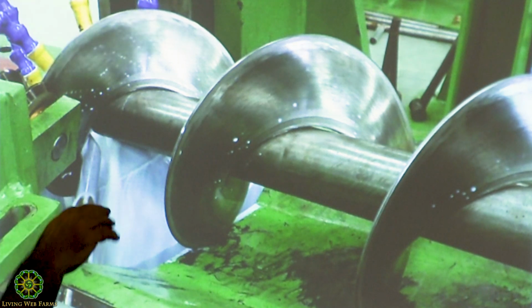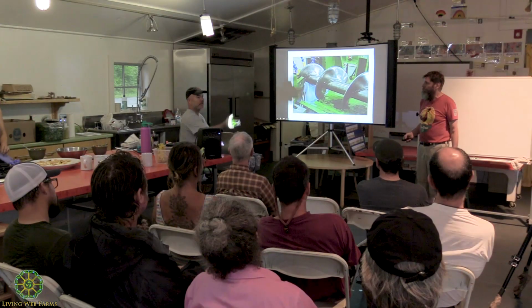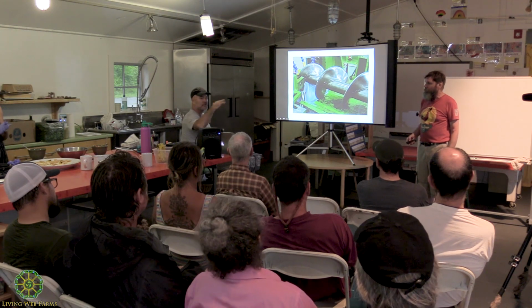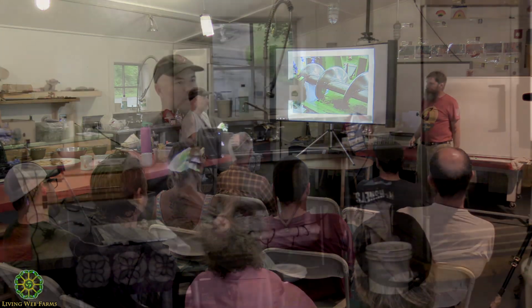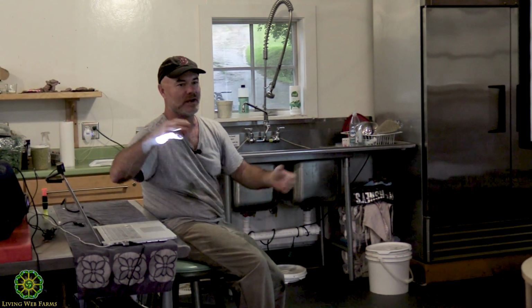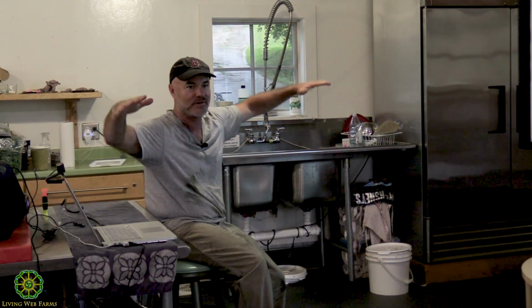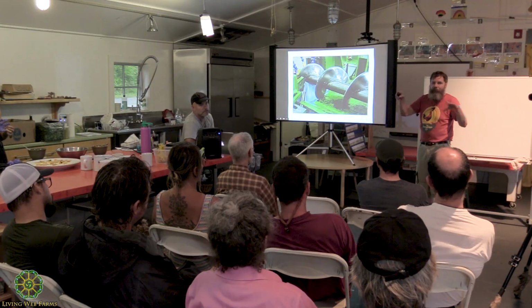If you lifted water over the draft tube, you've created a vacuum. Yeah. So you started that motion already, so you just need to move a very small section. Right. And that perpetuates it just like an airlift pump would. But once you move that water over the top of the draft tube, then all of the head pressure of the lake is pushing it back in. Yeah. So it just continues. It doesn't take much at the top to pull it all in.